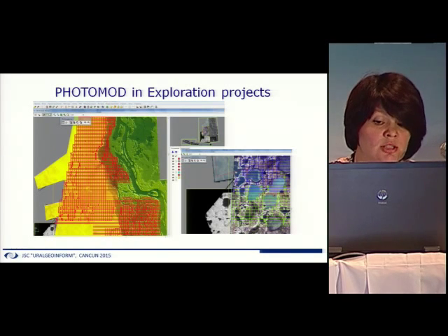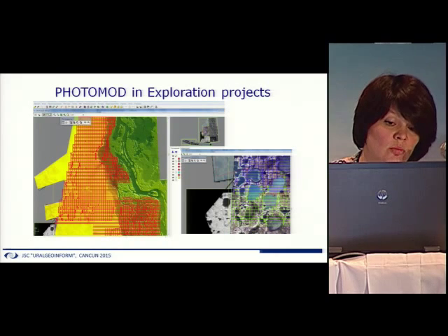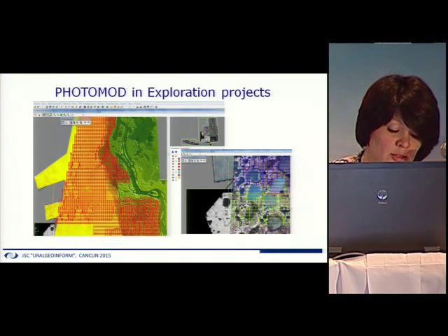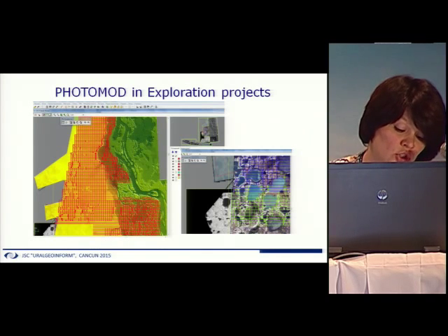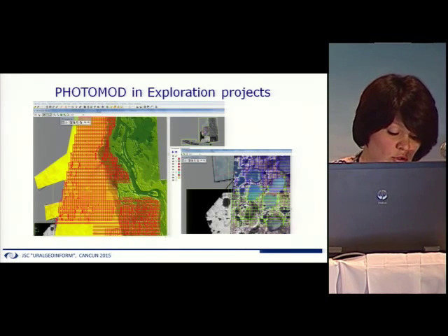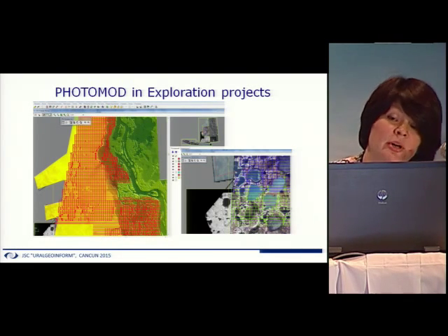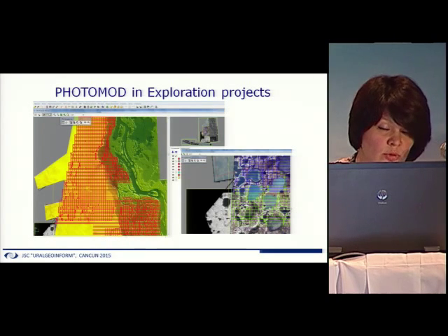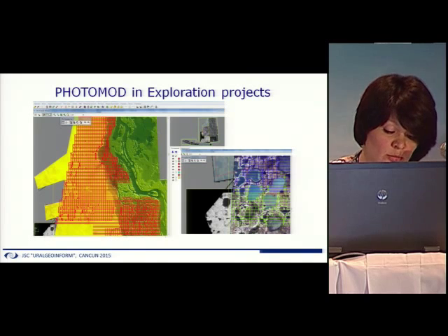We had already created 1 to 25,000 orthophoto plan. We had satellite imagery to rely on and digital surface model. Using PHOTOMOD, we specified added accuracy to the model, bringing it to 1.7 meters, and out of 570 points, we were able to control our digital elevation model and identified the third coordinate for missing 400 points.